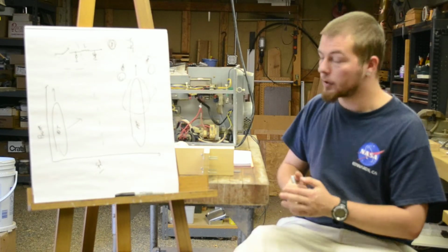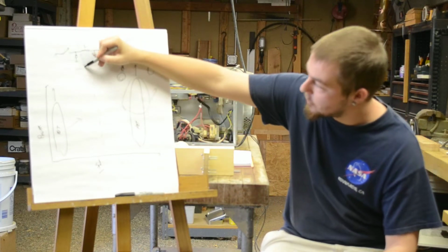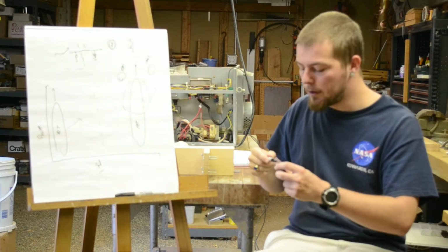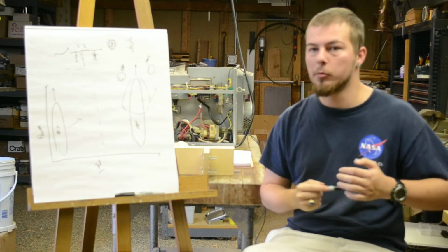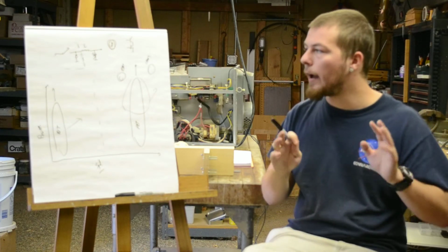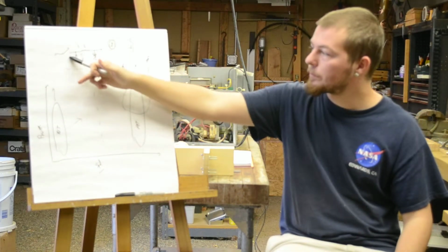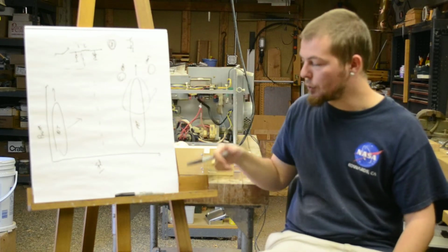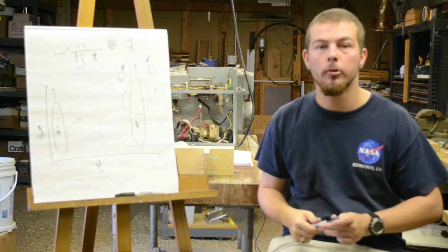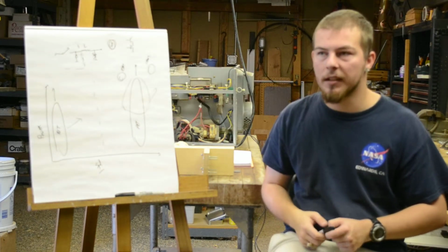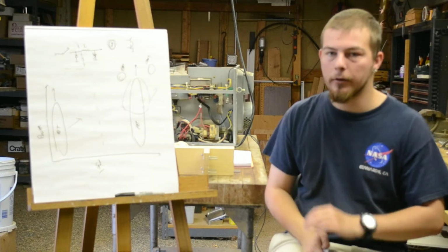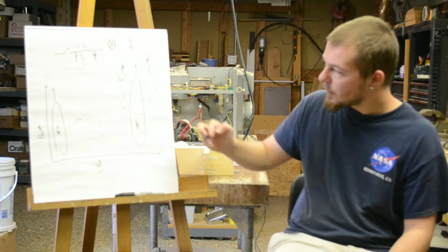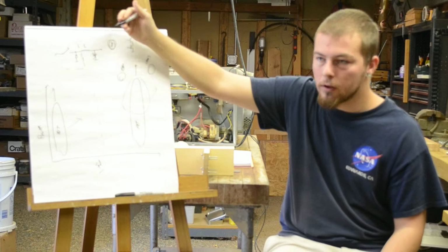You can basically separate the circuit into 2 different components. The first is the switching component, and oddly enough, in a lot of contexts, the diode is considered to be part of the switch because of how it interoperates with the transistor. That's why a lot of the times when diodes are specified in these circuits, they're designed to be hyper-fast switching diodes. That's not necessarily because the diode does anything, but because of how it interoperates. And finally, the coil, the inductor.